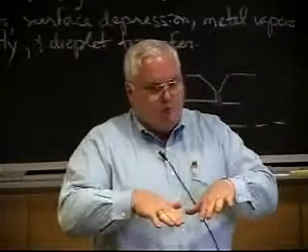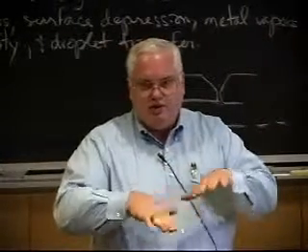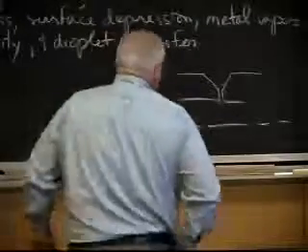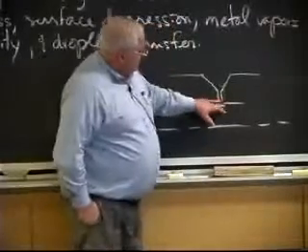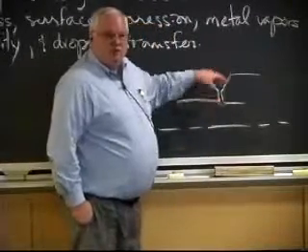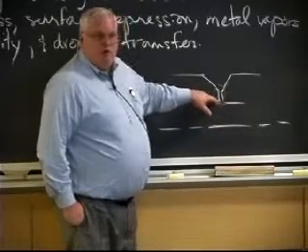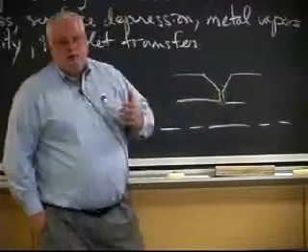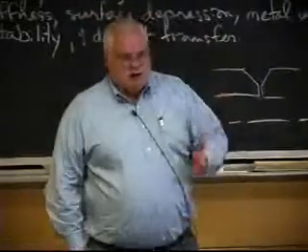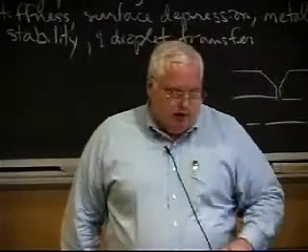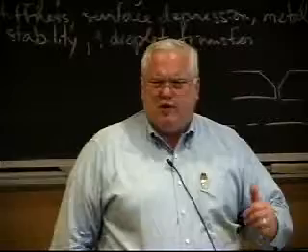If you just try to melt from the top, there are variations in the melting rate, and sometimes you'll melt all the way through. Sometimes you melt too far through and it drops through, and then you've got a defect you have to repair. And then sometimes you won't get full fusion and you'll have a lack of root fusion, which you pick up on x-rays or whatever. So there are lots of different types of defects.